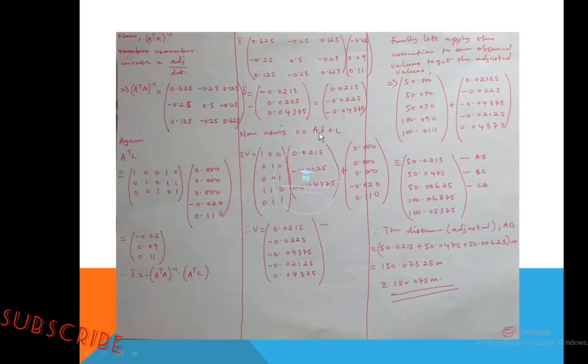actually we are getting to the end, which is the residual. Now V is equal to what? AD plus L. AD plus what? L. We already know our A, which is what? This 5 by 3 matrix. We already know our D, which is what we just got right now, and we knew our L earlier, which is the matrix of computed minus what? Observed, which is what you can see here.